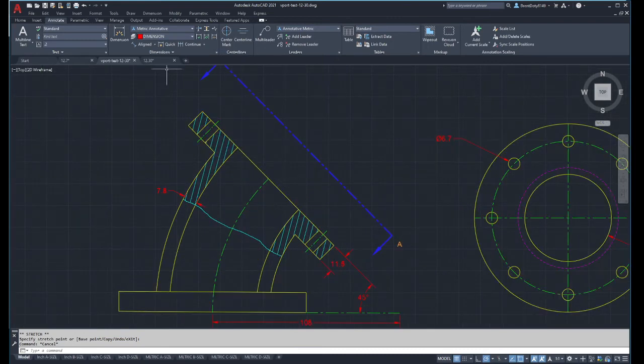That would leave me being able to go in here and put in, you'll notice I use the aligned dimensioning. The aligned version, what that does is the points have to be lined up or parallel with each other so that it works correctly. You can't use a linear, or it'll just give you vertical or horizontal.